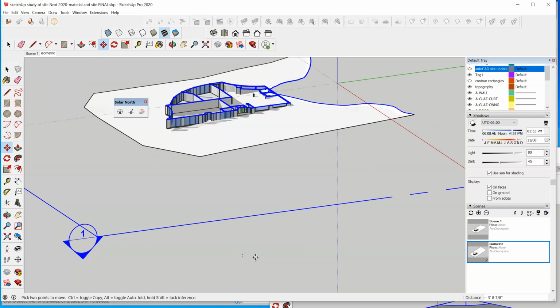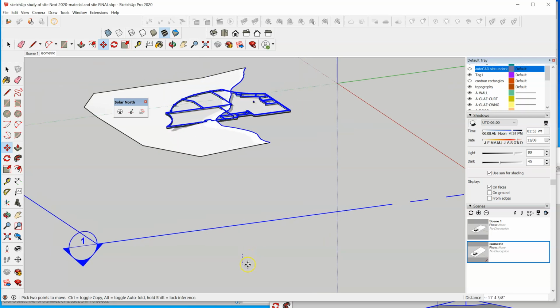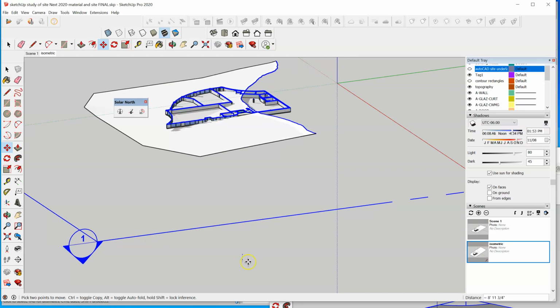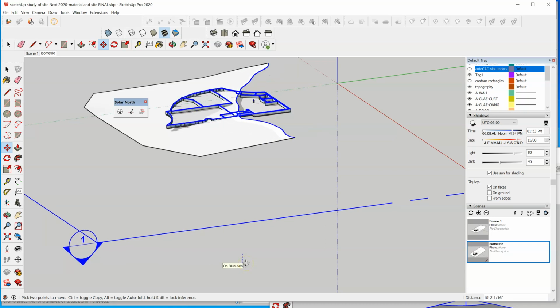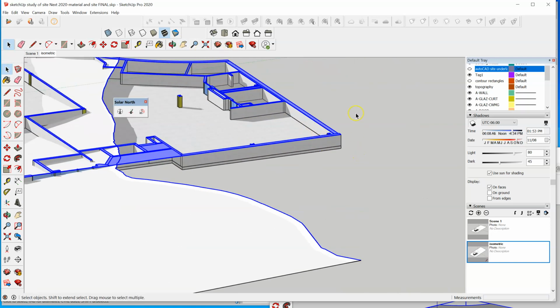We do have, when we're introducing topography, we quite clearly have the problem of how do we represent, if we were working in Revit, you'd create a building pad and that would create a depression in the earth. So we're going to have to deal with that separately or turn off that layer when we're looking at a floor plan. But I want this cutting plane to be about 4 feet from the finished floor. So this is going to be my level 1 floor plan drawing.